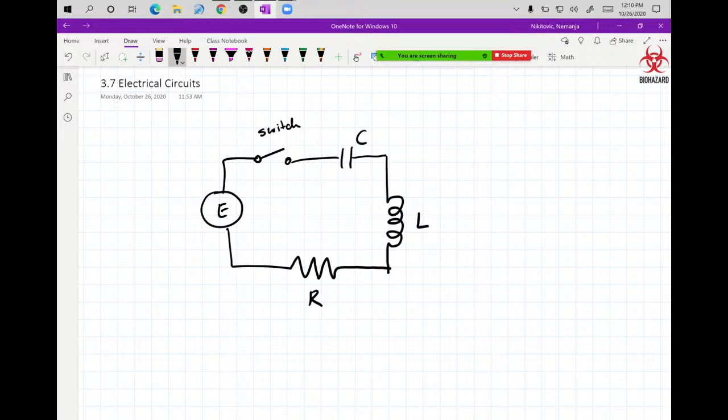We're going to start with E over here, and that one will be called a voltage source, or a current source. This is the equivalent of the plug in a wall. I don't want to say the battery because this is not direct current. These are alternating currents, which means that the polarity of plus and minus that you have on a battery switches according to the frequency at which the circuit is oscillating.